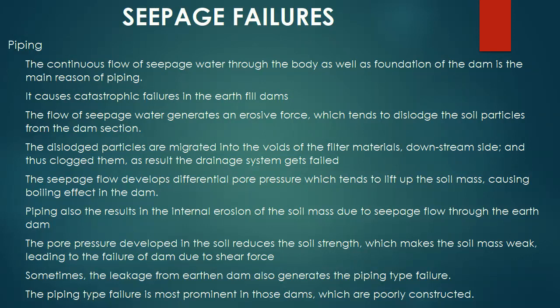The flow of seepage water generates an erosive force, which tends to dislodge the soil particles from the dam section. The dislodged particles migrate into the voids of the filter materials on the downstream side and thus clog them. As a result, the drainage system fails.